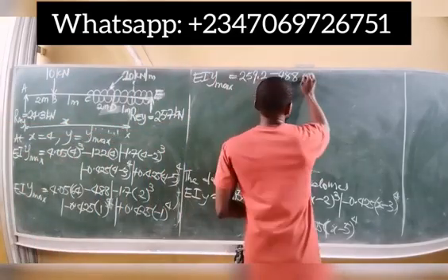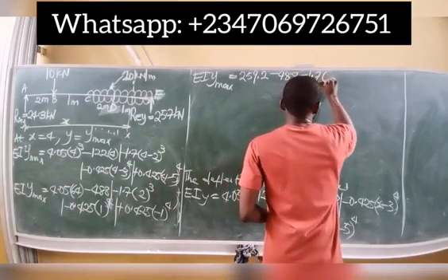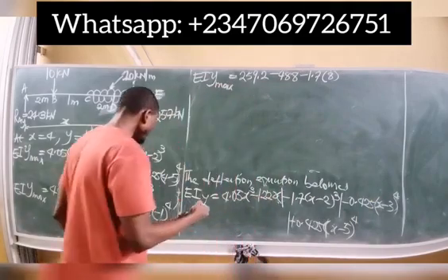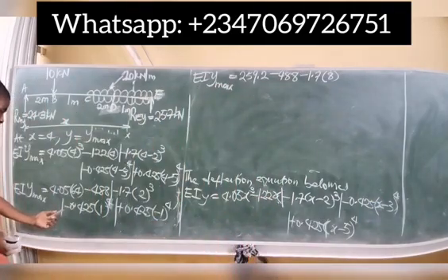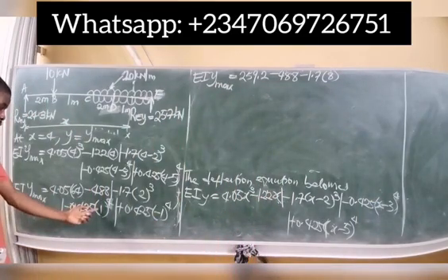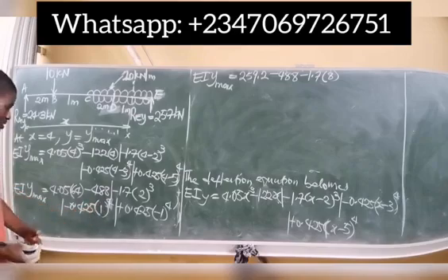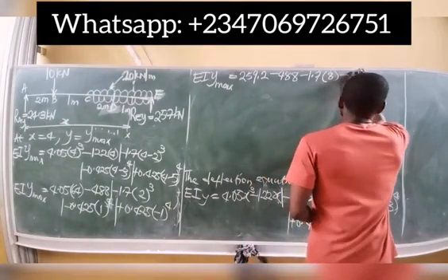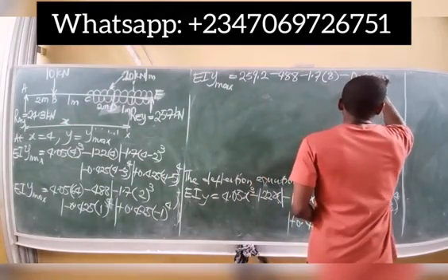So I simply have minus 1.7 into 2 to the power of 3, which is simply 8. Next Macaulay's bracket, I have minus 0.425 times 1. 1 here is positive and not negative, so it is greater than 0 and I can still work with it. Of course, 1 to the power of 4 still remains 1, so I will simply have minus 0.425.